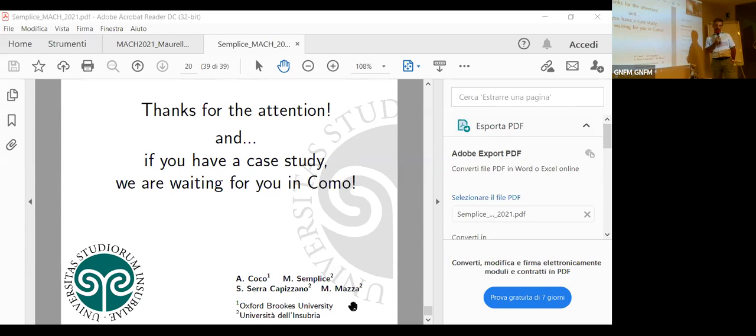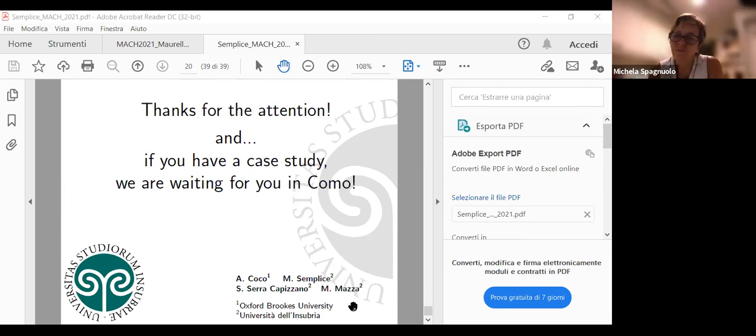And it is possible to move to adaptive meshes, and the choice typically goes into octree type meshes. So still made of cubes, but not all of the same size. But yes, in principle, you could implement a level set method on any kind of background mesh, which I just don't see the need for. Yeah. Maybe you have a good taste.